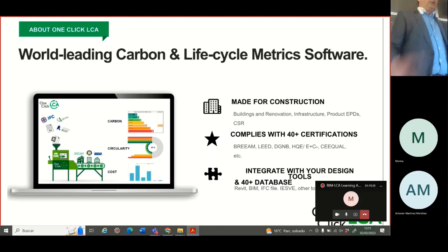And I'm telling you again, the database of products is the key, because for many products, it's so hard to find. Only a few companies in Europe have an EPD. You ask many producers for the EPD, and they ask what an EPD is. So it can sometimes be a barrier for products used inside the building. If there is no EPD, you can still have the building, but you're losing points in certification.